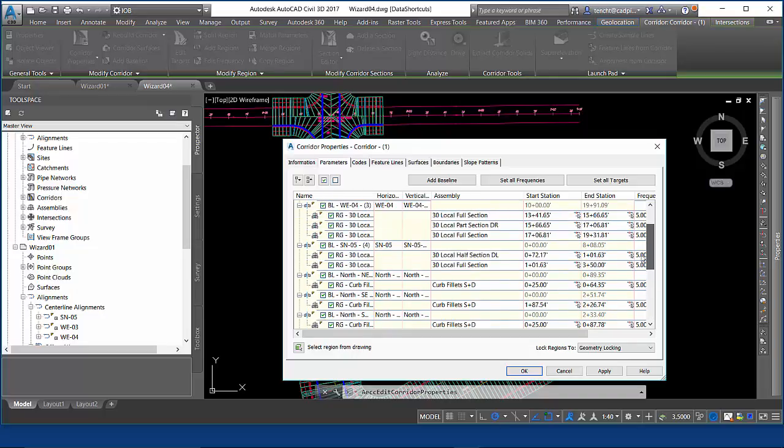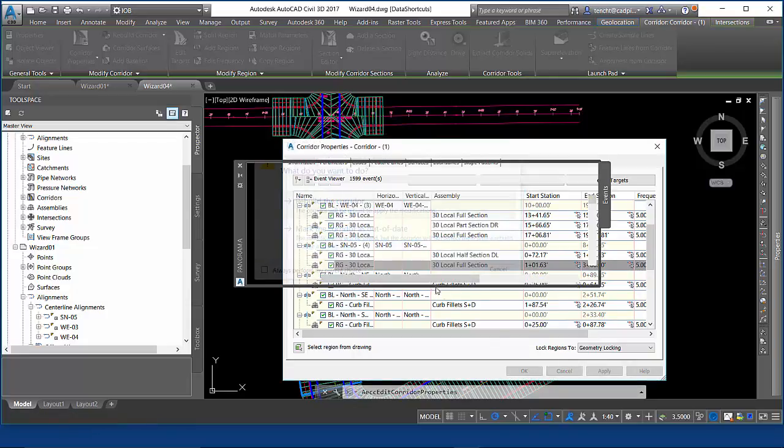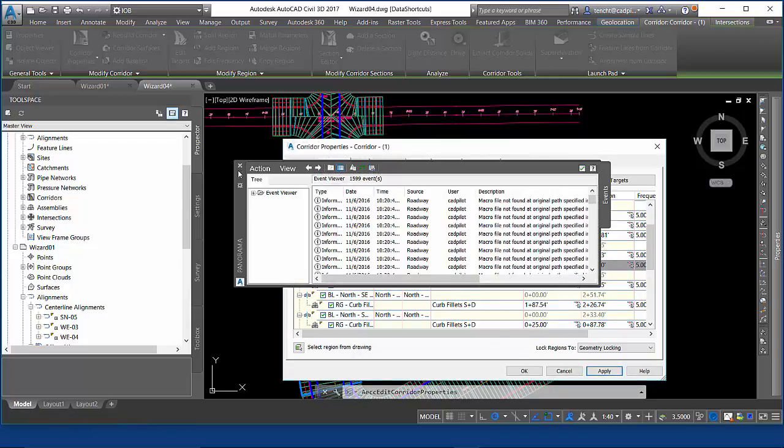And my other south to north section, I want this value set to 300, so my regions are meeting at the same point, breaking at the same point, but ignoring whatever is going on horizontally and vertically beyond them in the corridor. And this will make my corridor actually work. So I end up with a surface.